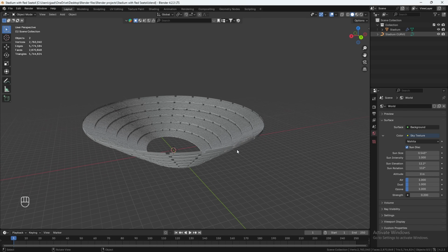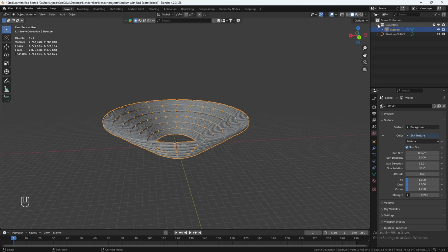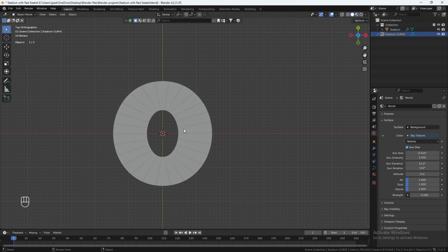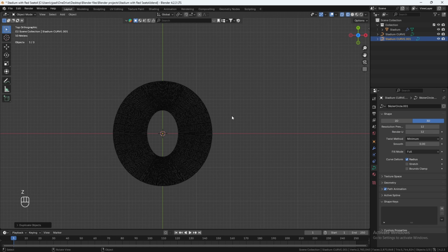Okay, so I've reached the 30-minute mark on this tutorial, so let me just quickly add in a ground and a building to cover this entire stadium. Let's go to top view. Let's click our stadium curve. Let's do Shift T, duplicate it, and then escape to put it back in place. Change the resolution to 12. We'll go into wireframe, hit S to scale it down.